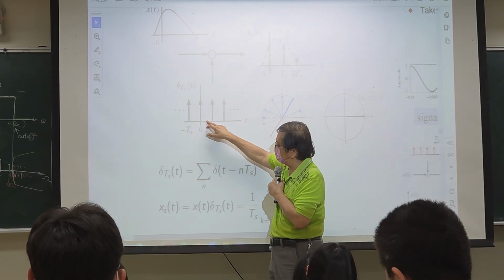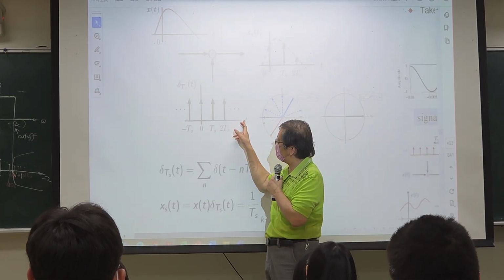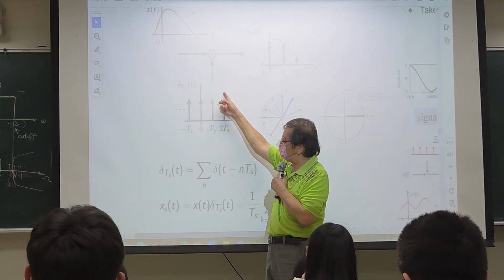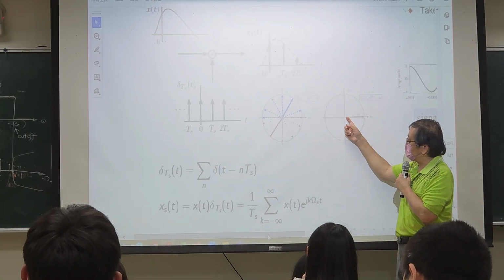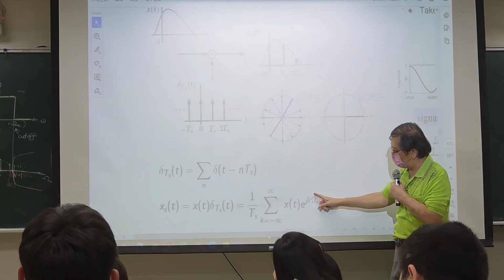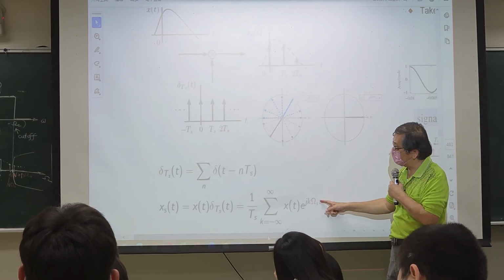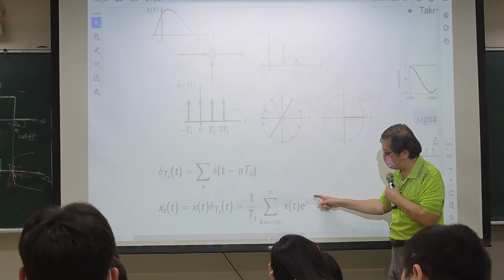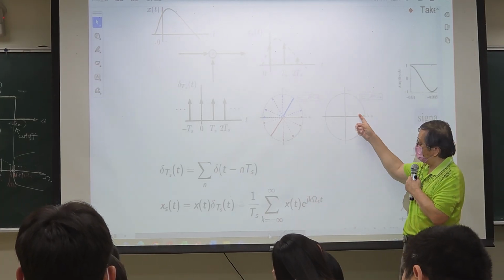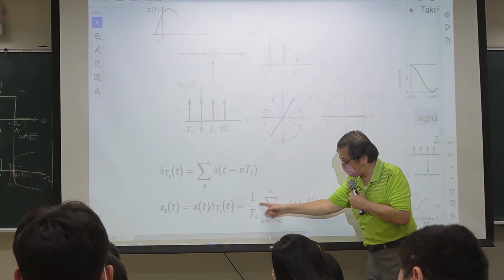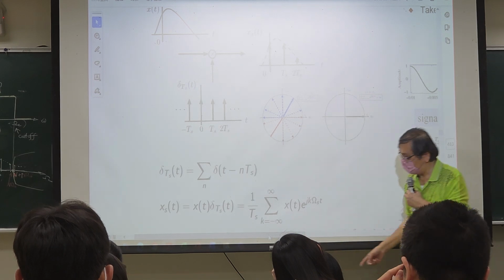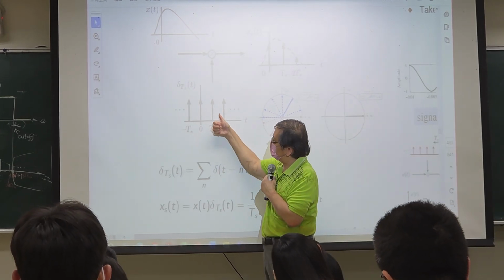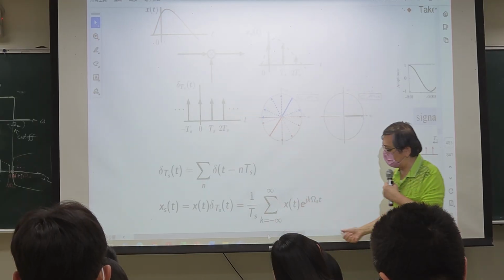Nothing here. But when the time equals a multiple of the sampling time, it goes to infinity. Because you sum up all those terms, each is equal to 1. At t equals n times Ts, this complex exponential function is exactly 1, but you have an infinite number of terms. So the summation goes to infinity. Okay? That's a very interesting result.